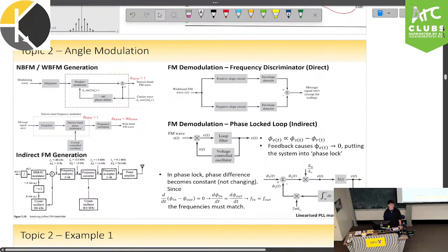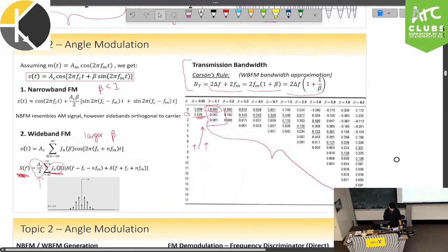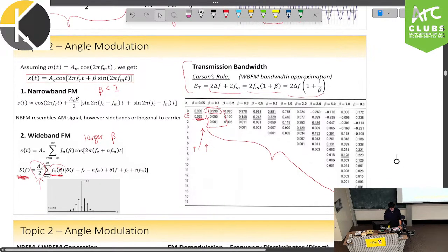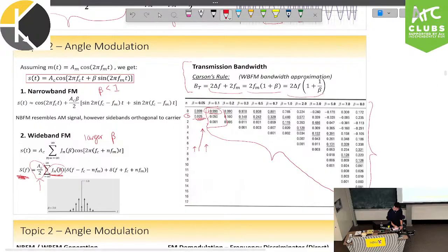What's the physical significance of beta in modulation? Well, when you have a larger beta, you can see that you have a larger allowable range of frequencies in your modulated wave. So I would say that is the significance. Narrowband is saying that you're not allowing many different frequencies in your modulated wave, whereas wideband, when you have a larger beta, is allowing a wider bandwidth, I would say.